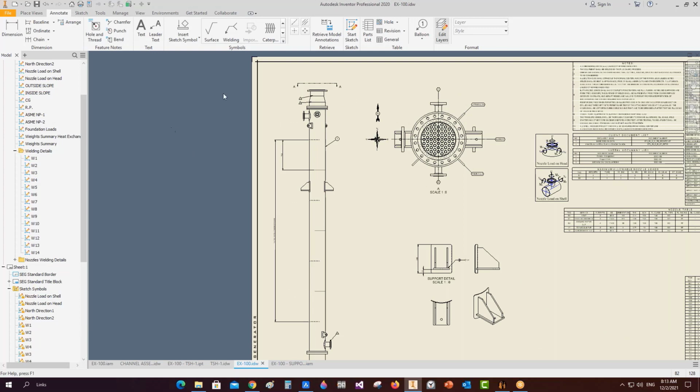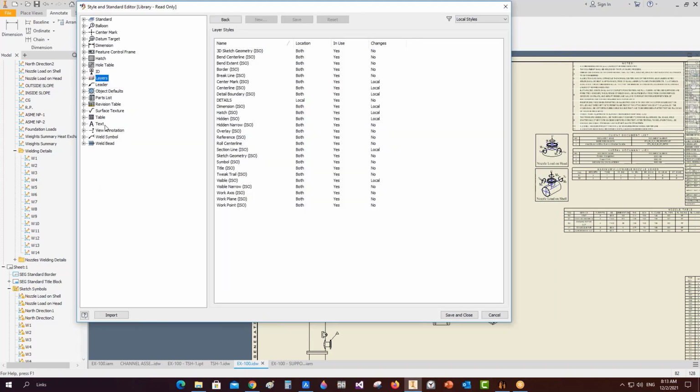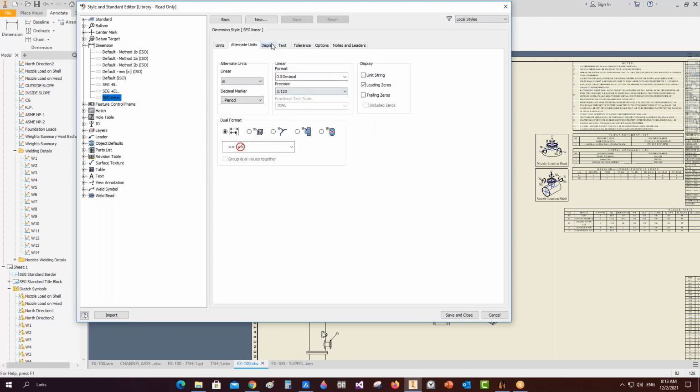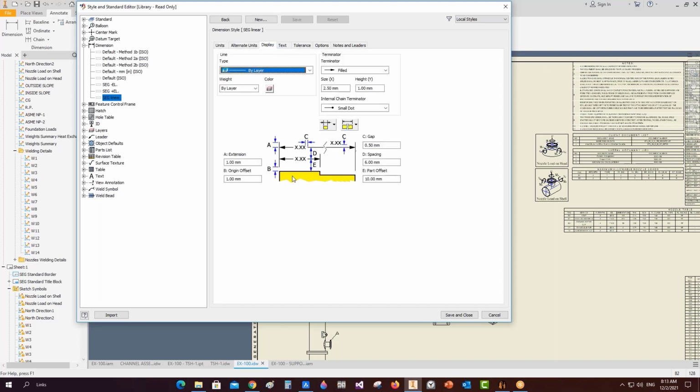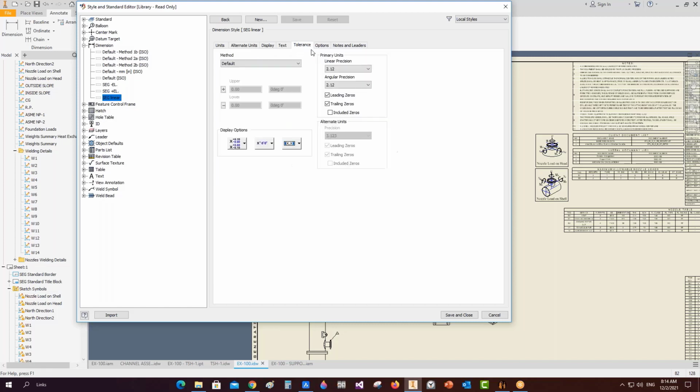Okay, so the same thing here for the layers as we discussed, and the dimensions. We open here that's the SEG standard. If you open the dimensions from here, for example, and if you open the linear dimension, you can control the text and the style of text. You can control all of this, the gap, the style of the text. Okay. We got it.